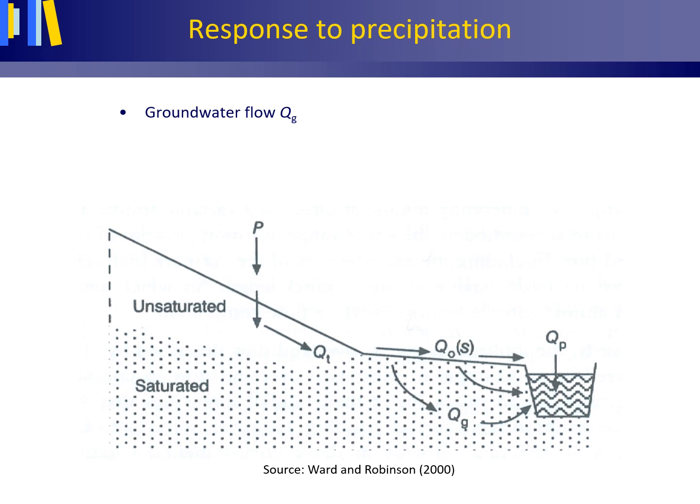However, when the wetting front reaches the fine textured layer, the percolation capacity will be controlled by the fine textured layer and will drop sharply. If percolation continues, a perched water table may develop in the coarse soil above the impeding layer, which in sloping terrain may result in through flow, subsurface soil water flow parallel to the land surface in the direction of the